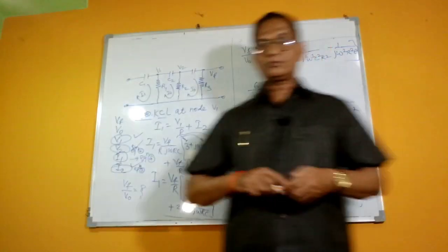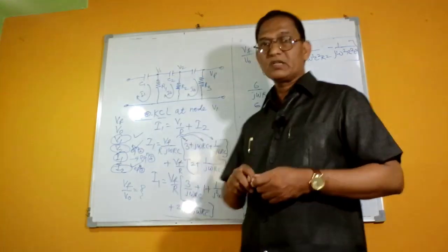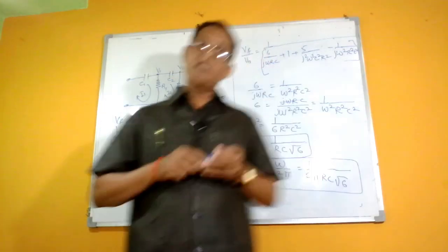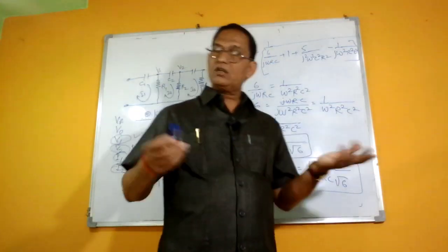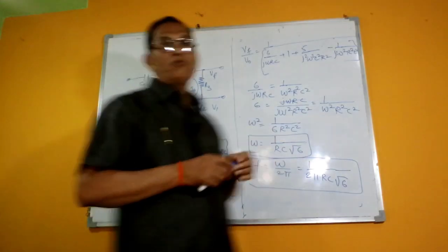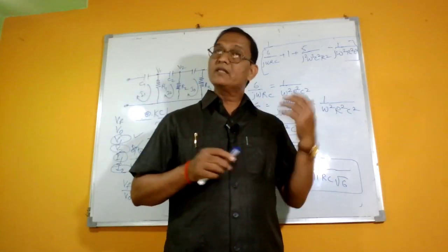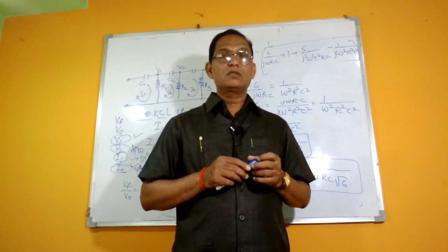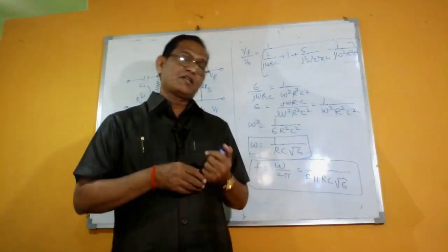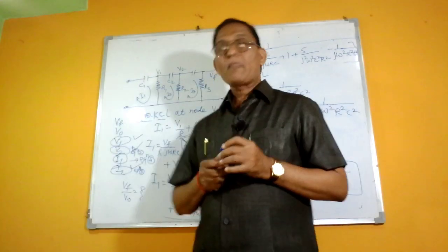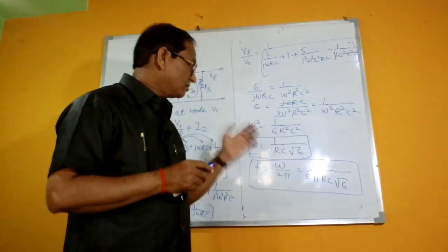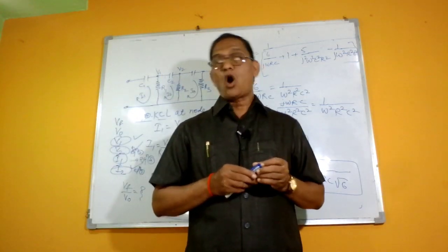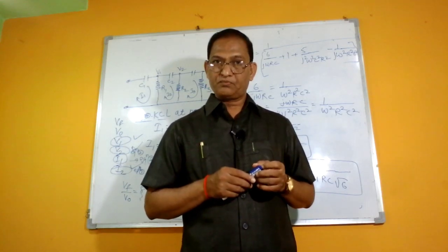Okay, so it has advantages over the LC oscillators. This phase shift oscillator has advantages over the LC oscillators, as in this case we are not required the coils, the inductances L1 and L2. This gives good frequency stability and a good sine wave, and also one of the best advantages of this oscillator is that it can be operated for low frequency also.